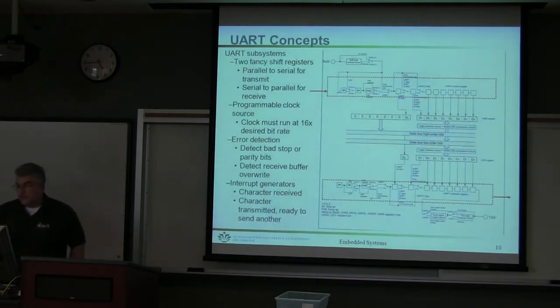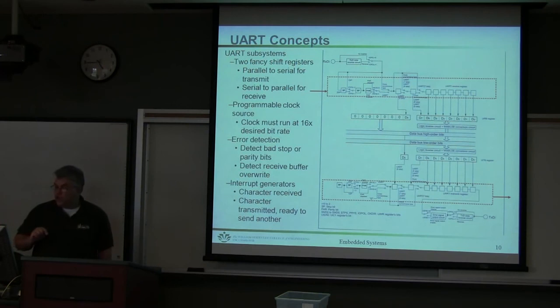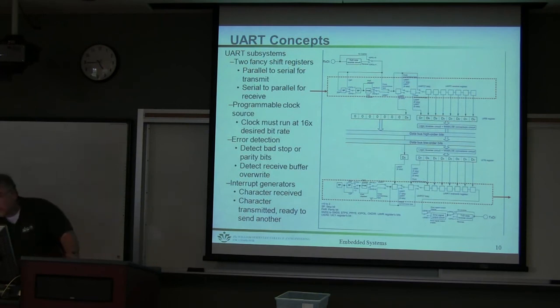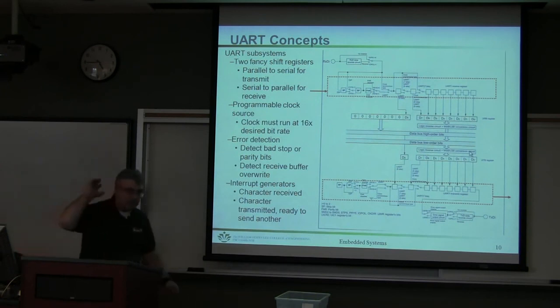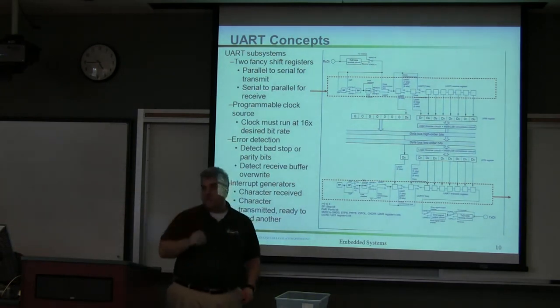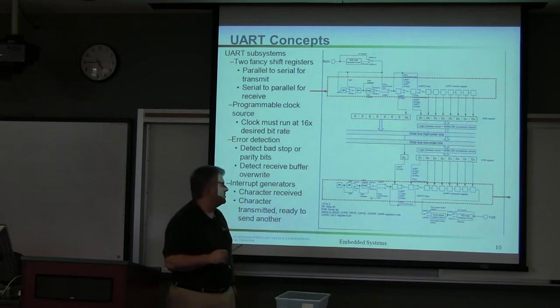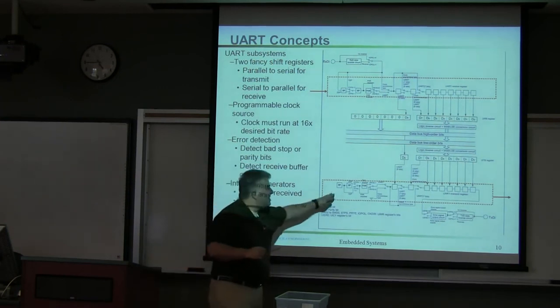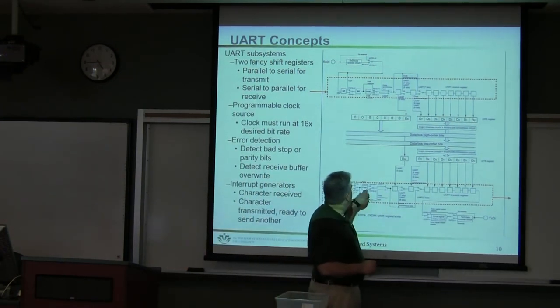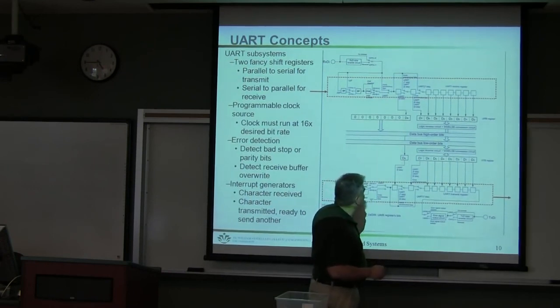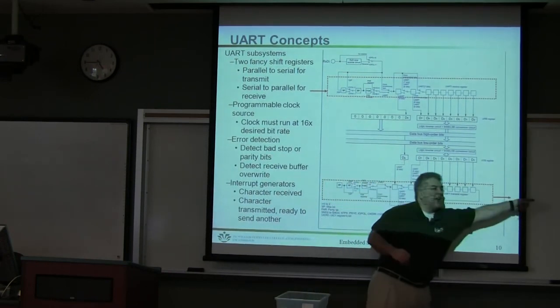Literally, all you have to do is say, I'm going to write at this memory location 8 bits of data. I'm just going to write a byte to a specific peripheral interface port. Then the hardware itself will add the parity, add the start and stop bits, and send it out.